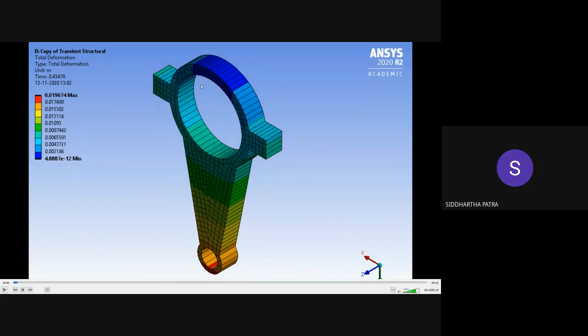Basically, I would have a knife edge on which I would simply put this connecting rod in this configuration. So automatically, the highest point would be the pivot point, and I would let the connecting rod oscillate about its pivot point. I should also be careful that the amplitude of oscillation is quite small, so small that sine theta could be approximated as theta, which is approximately 5 degrees.